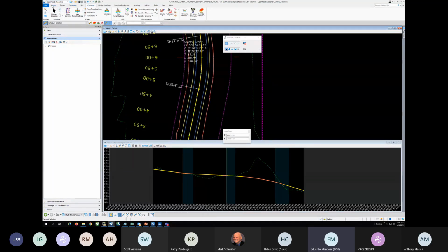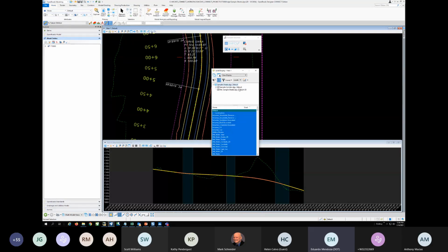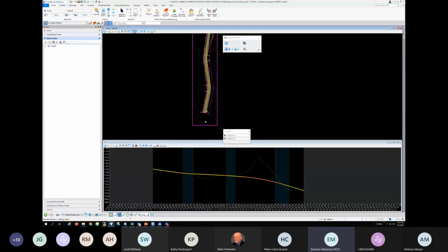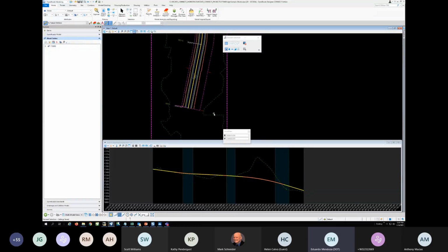So going to Home, Levels, underneath the corridor to geometry. Here's my levels. And I'll turn on 500, 500, and ticks minor 50. There we go. Okay, I'll do a quick save settings here. Okay, so we've got the corridor there.